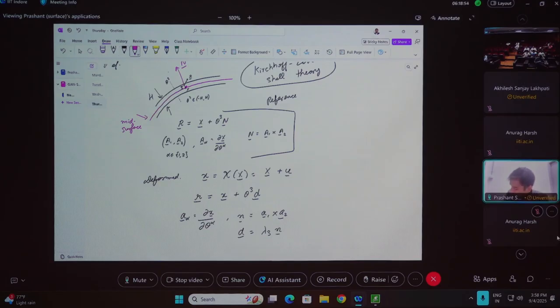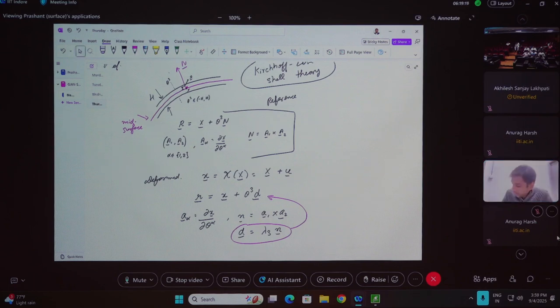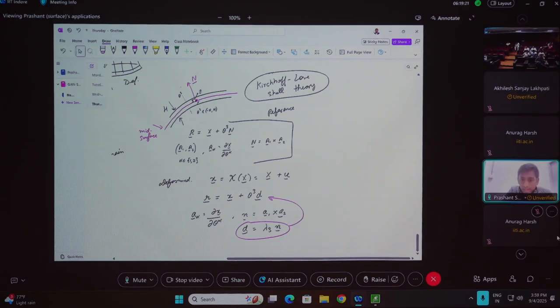So this is what goes into the position vector. It says that when you do a large deformation in the shell, it might get thinner, so you need to account for the changes in the thickness there. This is a very systematic manner in which you can write down the geometry of the shell, and then you can follow a very similar approach in differential geometry that we said earlier.